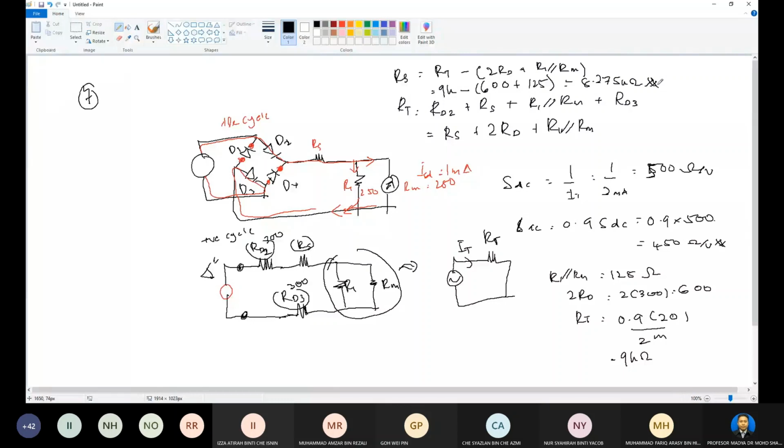If the voltmeter uses half wave rectification and a 100 microampere meter movement, and it is set on its 10 volt range, and if Rm equals 1.5 kilo ohms, what reading will be obtained? That means the value on the meter movement.